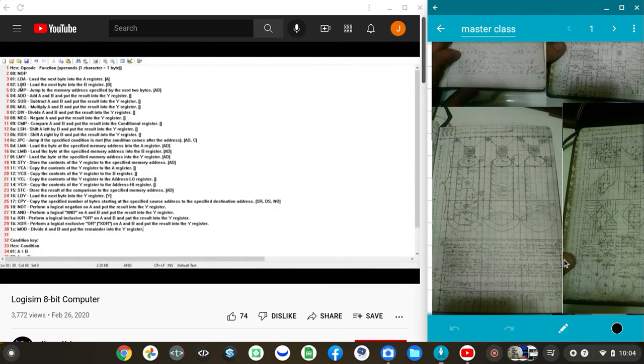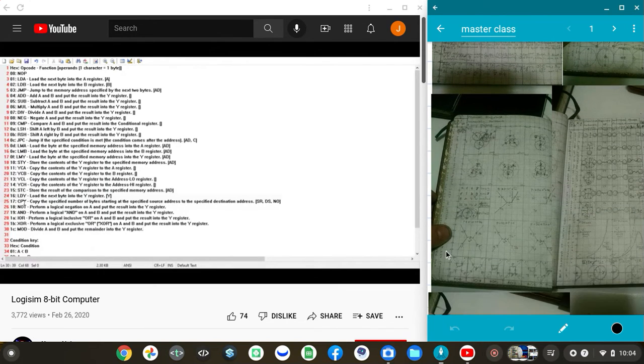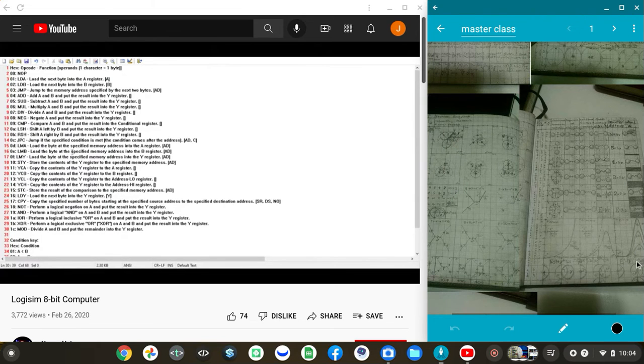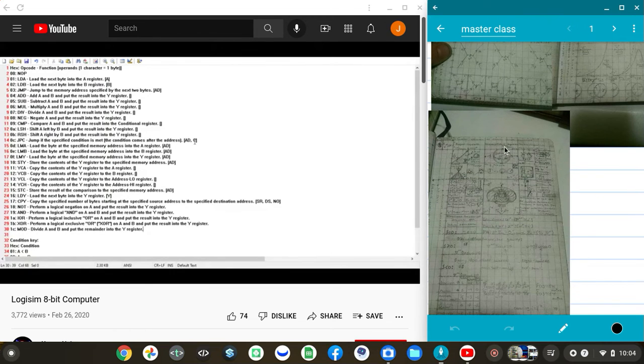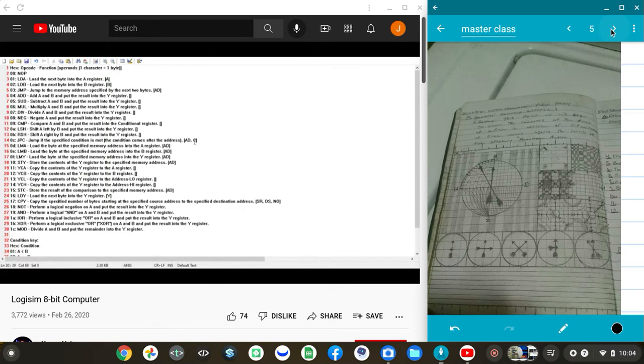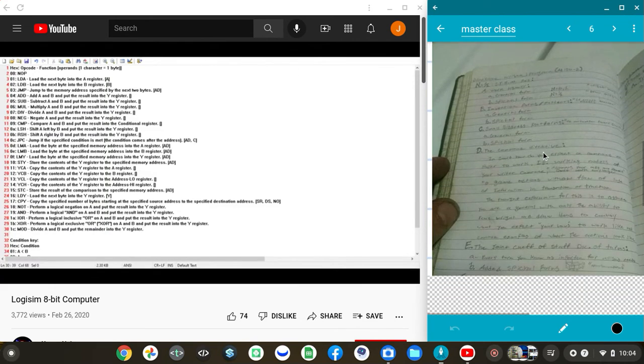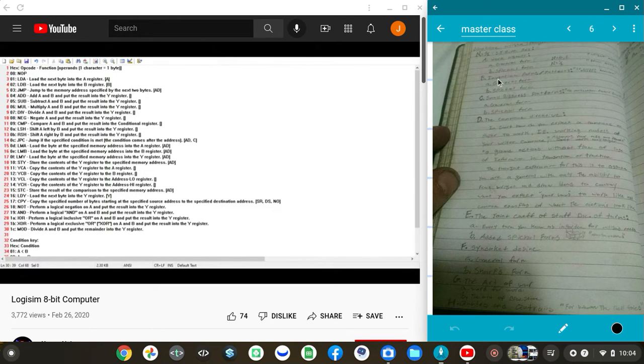Now, an example of a really long instruction is the copy instruction. Except, it's a little bit different. I'll get to that one in a second, so I'll instead draw your attention to the jump conditional. Jump if the specified condition is met. So you've got 2 bytes for address and a byte for the condition of whether or not to jump. So yeah, that takes, I think, technically 4 cycles, because on the last cycle it's actually doing the jump. And yeah, so that's one of the longer instructions. And I'll go ahead and get back to the CPU.